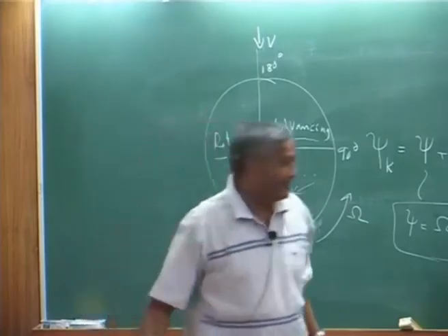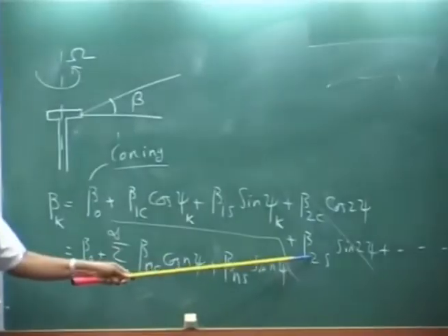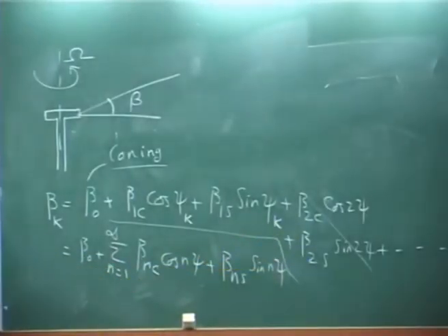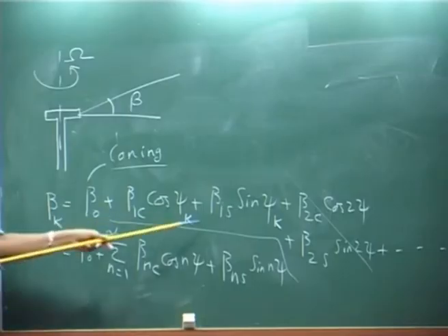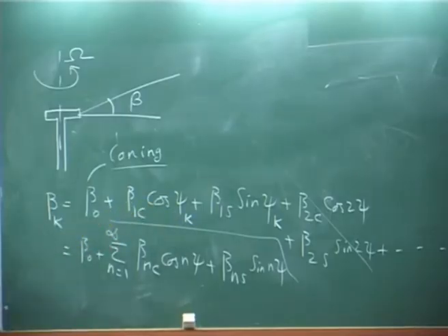But when you go to higher harmonics, these are all like warping of the plane. It is like, you know, a corrugated sheet, right? It is that motion. Now you see the complex representation of that plane. I don't look at that warping. I look at only the mean part. Okay. So the rotor disc, now please understand, without this you cannot fly the helicopter.